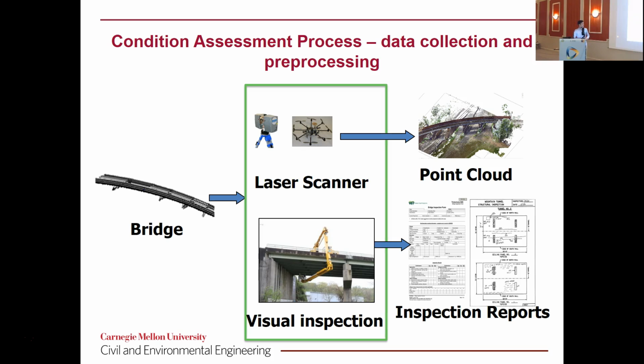The method we're going to be focusing on more specifically is the laser scanning method, in which we can install terrestrial land scanners at several critically selected points around the bridge, or we can get a UAV and attach a LiDAR scanner to it to eventually create a 3D point cloud, which contains X, Y, and Z coordinates and RGB information for each of these points.